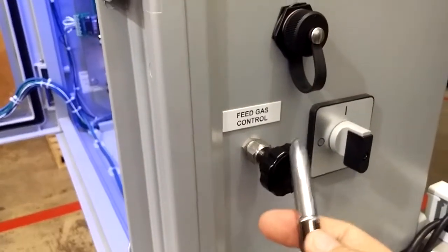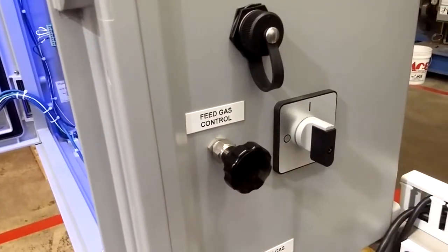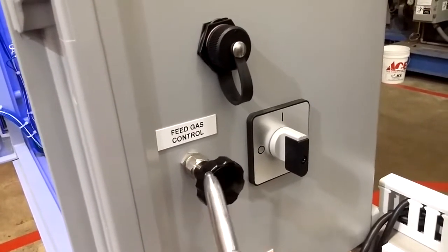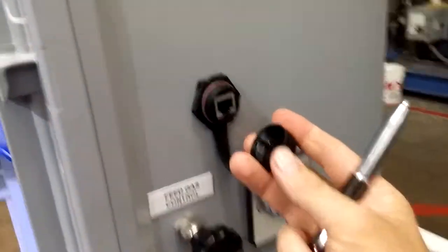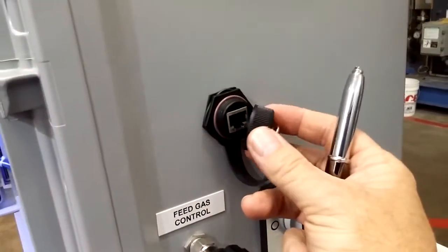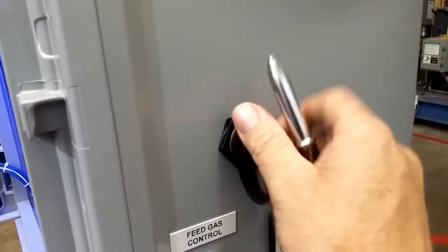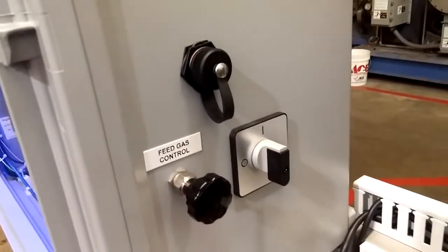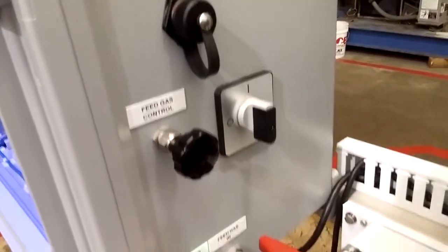On the side of the generator, we've got a feed gas control. This is what regulates the gas flow through the generator. Like I said, the pressure regulator will automatically readjust pressure to maintain our target if you readjust this. We also have all these systems, as I said, Modbus compatible. We have an Ethernet port on the side and a bulkhead fitting where you can connect a computer, SCADA system, or a technician can plug in a computer with the maintenance software to troubleshoot any changes or upload new programs to the PLC.